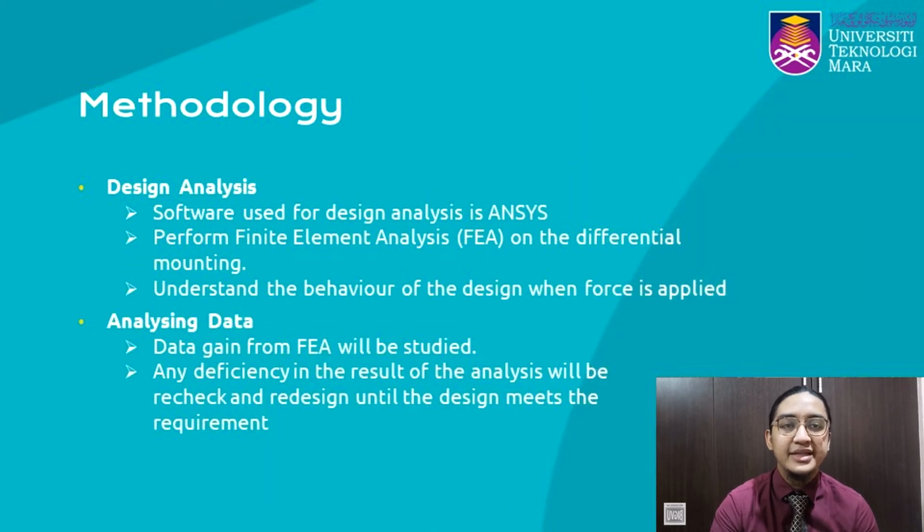The next phase is design analysis. To analyze the design, ANSYS software will be used. Finite element analysis (FEA) will be performed on the differential mounting design. FEA is a technique used to predict the behavior of various types of physical systems, like deformation of an object affected by vibration or applied force, by using a computer. With correct input, meshing and boundary conditions, the result of the analysis can be nearly as precise as performing the test physically.